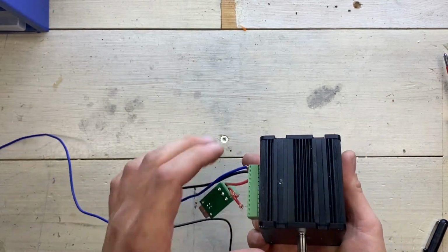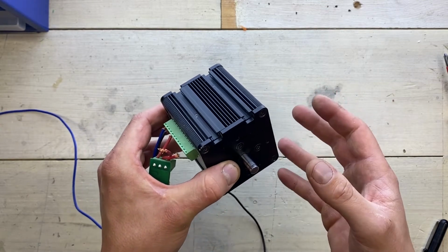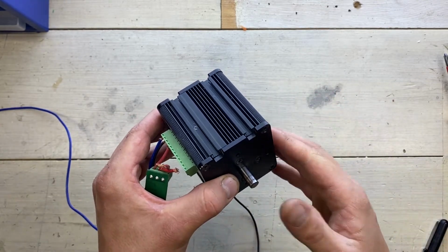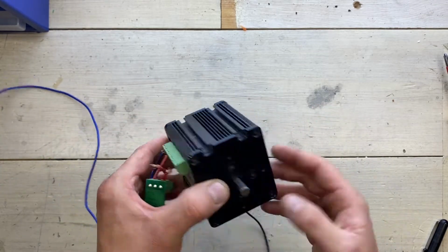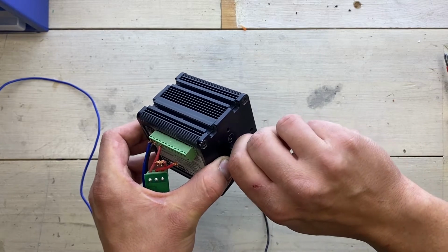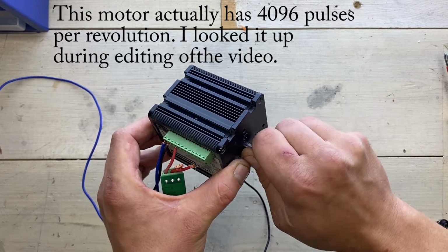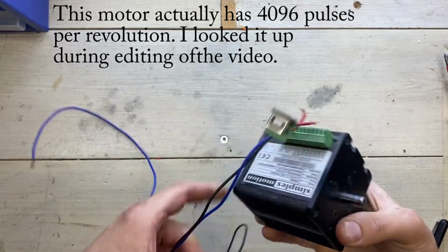And the pulse encoder gives a specific amount of pulses for every revolution. Generally we're talking binary resolution here, so 1024 or 2048 is quite common, and that means that we have 1024 or 2048 pulses for every complete revolution of the motor.